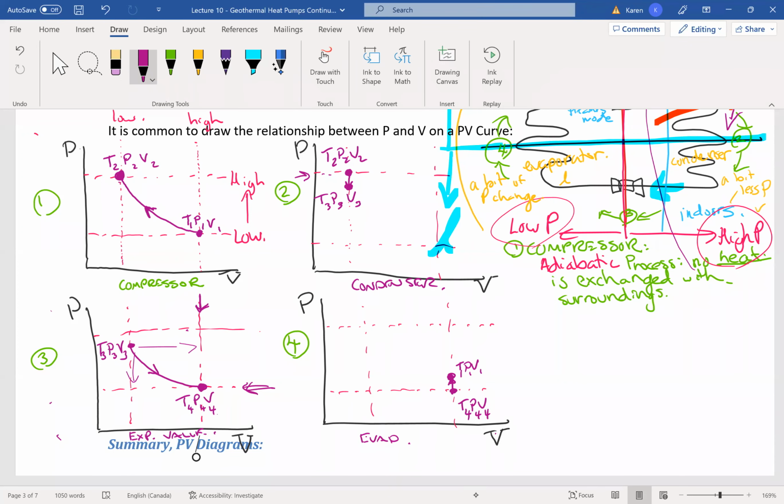Any questions about that? Points 1, 2, 3, 4 going across compressor, condenser, expansion valve, and evaporator. Pressure volume. In your other class, you did pH curves, pressure times enthalpy curves. And if you remember, that's when you had this diagram. I think, Jack, what you showed, or I don't know if it was Jack or John, looked more like a pH curve with some losses, which is what you did last semester.